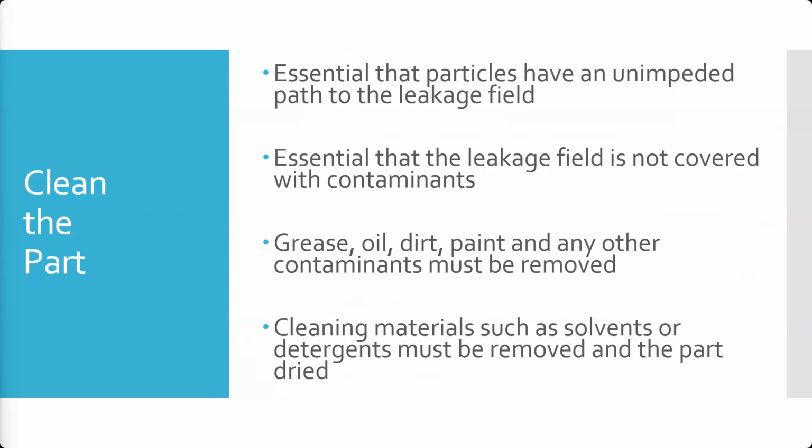The carrier solution is very similar to mineral spirits, but it's not exactly the same as the mineral spirits that's in our wash tanks. So we don't want to be introducing the mineral spirits into our carrier solution and have it potentially react with the magnetic particles or do something funky there, right? It has a certain viscosity. It has a certain lubricating property. It has a certain ability to carry those particles correctly. Okay.